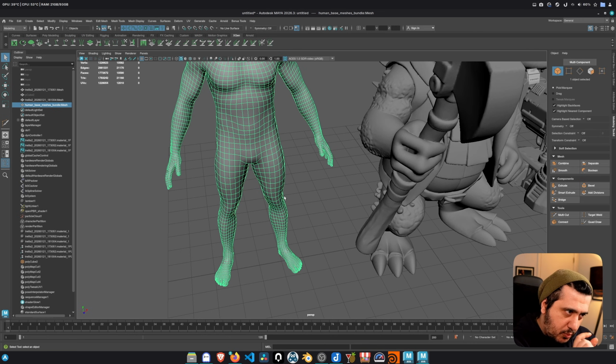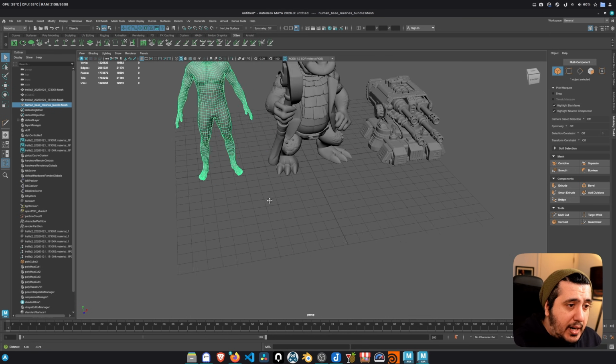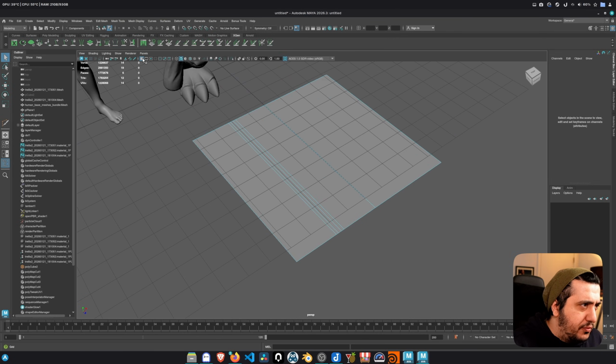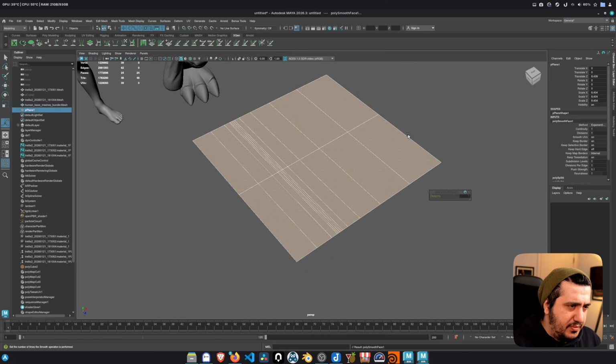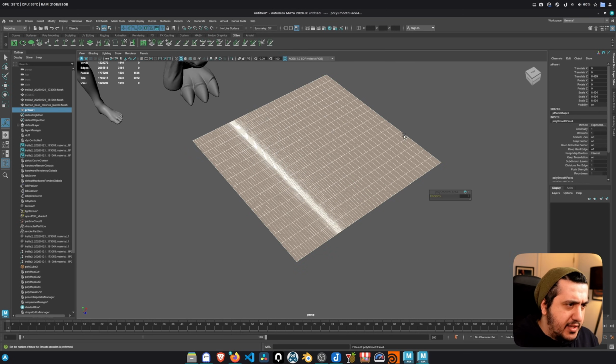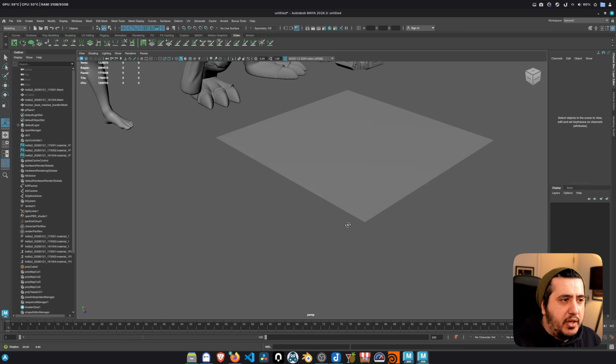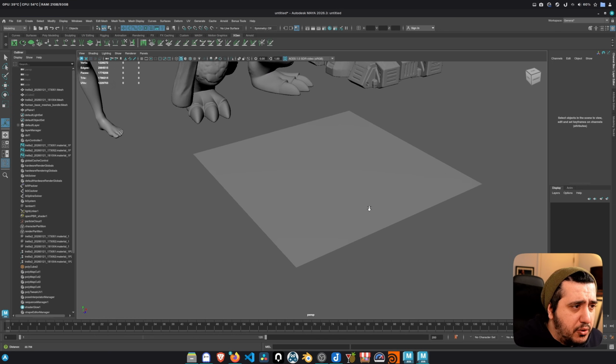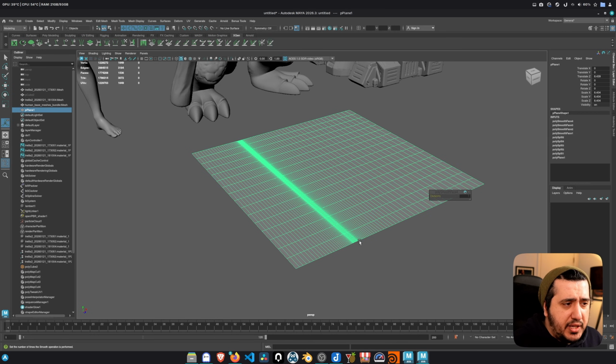Our smallest polygon is going to get smaller, and then we are going to be able to add finer details, etc. One reason is, if I take a plane like this, okay, let's turn off the grid. If I subdivide this, even on a flat surface, I don't know if it is visible in the recording, but first of all, I am going to get some weird shading problem in this super dense area.